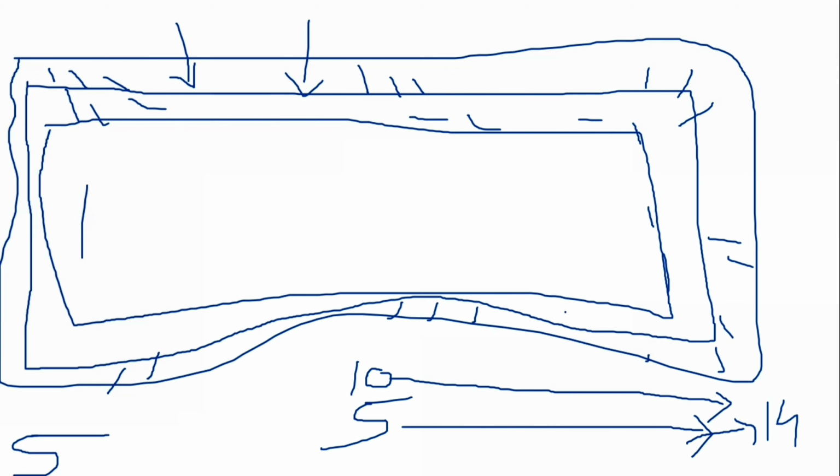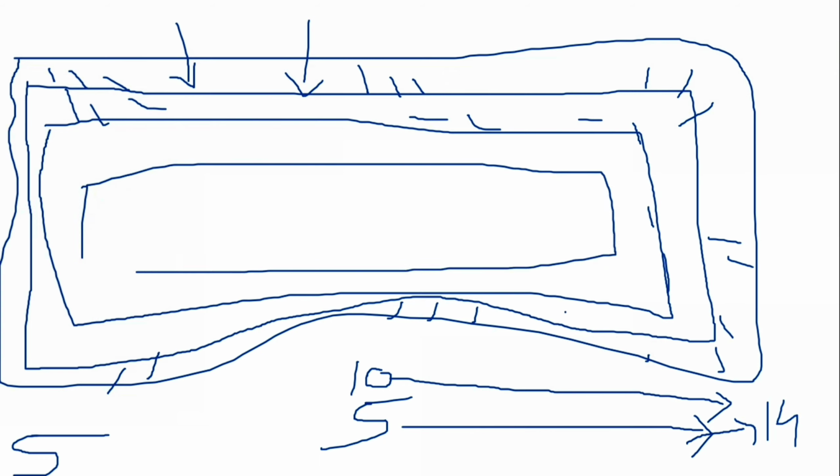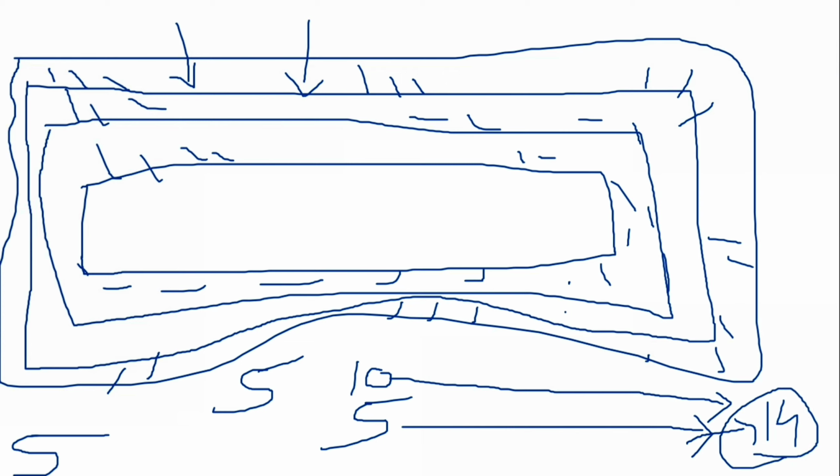So here is your third stage. Again, I provide a Wellpoint system at any location, and that one also lowers your water table by up to 5 meters. So after providing 3 different stages, and during each and every stage I lower my water table by up to 5 meters, I have my final result. That means right now I have the water table below 14 meters, that means up to 15 meters. Okay. So this is the condition of how we use the multi-Wellpoint system.